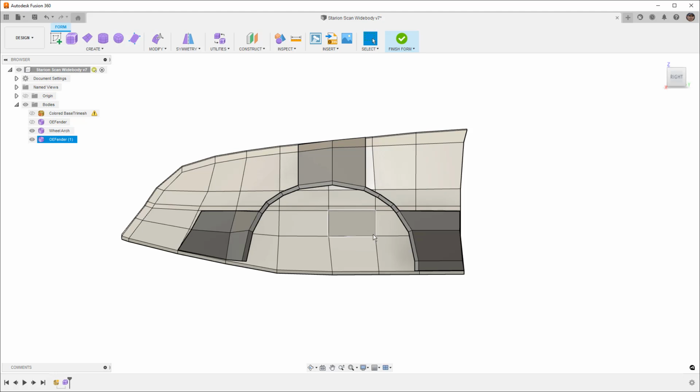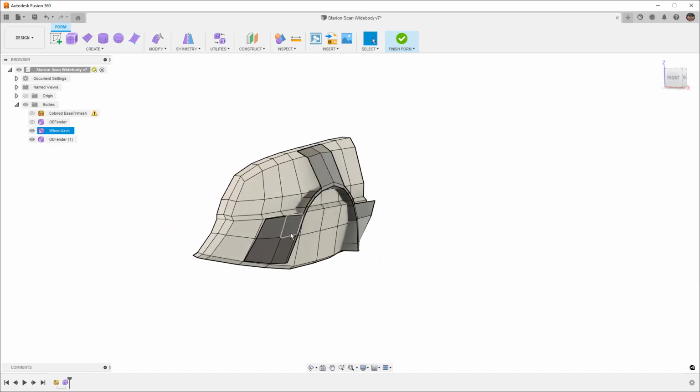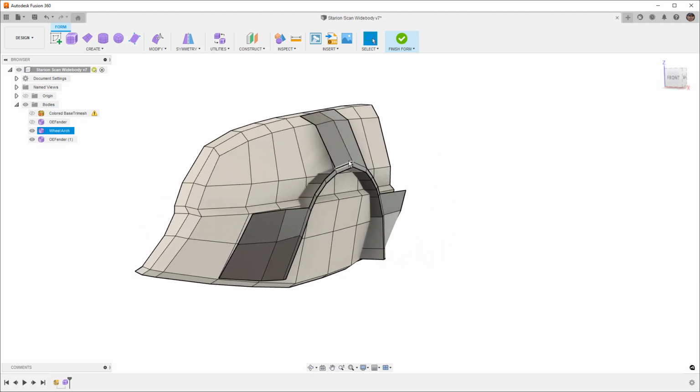But if you take your time when you're starting and you work methodically, you try to keep the number of faces as low as possible, you try to keep the spacing fairly consistent, and you work with things like copies of the bodies that you're working on, you start to build out the rough shape with this low polygon model. Later on, once we have the box display looking roughly like we want, that's the time when we go back and start adding additional edges and controlling the shape a bit more. But if you try to do it at this part of the design, it's just going to be too hard to control. You're going to end up deleting a lot of work anyways.